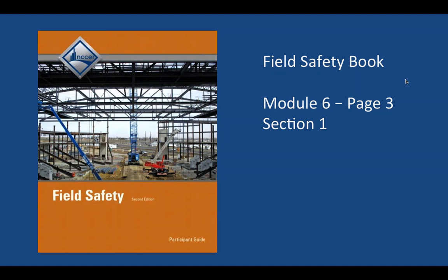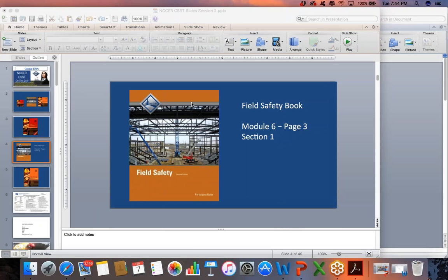All right. So controlled deck zones, right? They can be established for work areas, and it's going to be at least 15 feet tall, but no more than 30 feet to the next lower level. So what does that mean? That basically means that we can only go two additional levels, right? So let me show you what I'm talking about. I think I've shown you this once before, but I'll show you again.